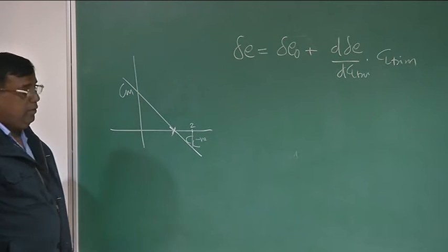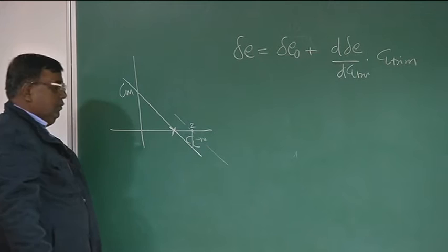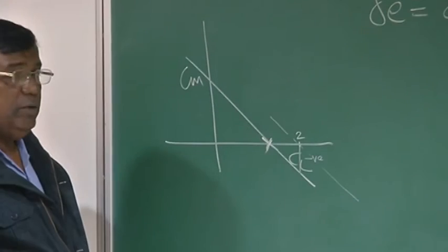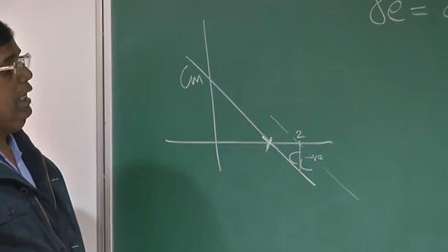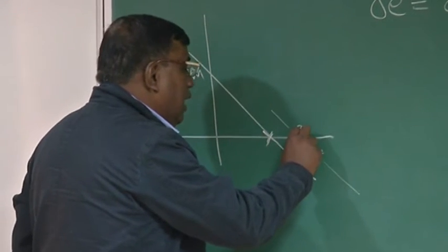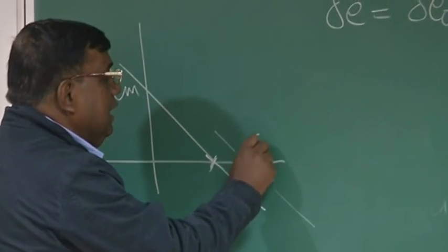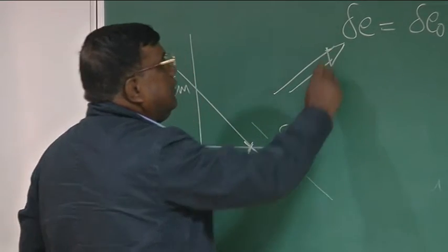So I need to nullify that so that this line becomes like this. To neutralize that negative pitching moment, I have to generate a positive pitching moment. And for that, I have to put elevator up, right? So how much elevator up is required for this CL trim, we will calculate from here using this.